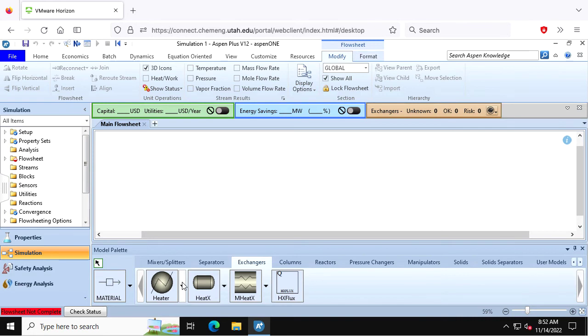Okay. Yeah, so it's an important thing to understand that centrifugal pumps are, I always describe them as a fan for liquids. That's not really quite doing it justice. But the key is that if you have your centrifugal pump and it's turned off, let's say, and you put a bunch of pressure on the outlet, you can actually push fluid backwards through the pump just because it's not super tight tolerances.